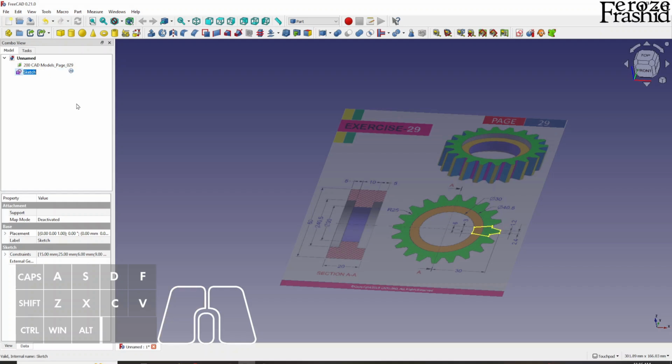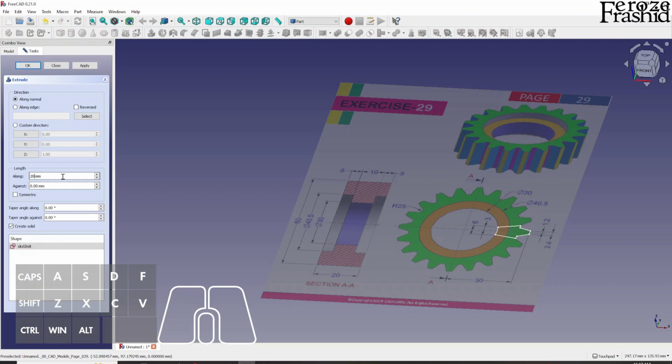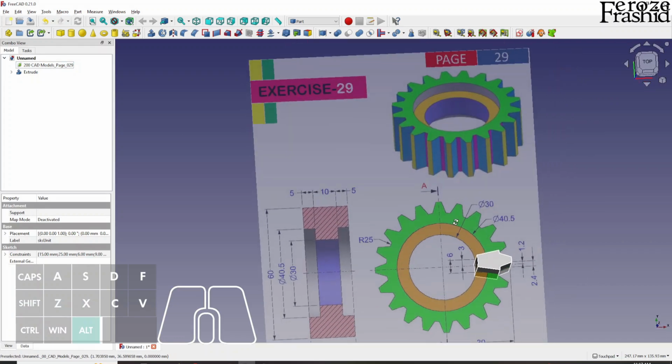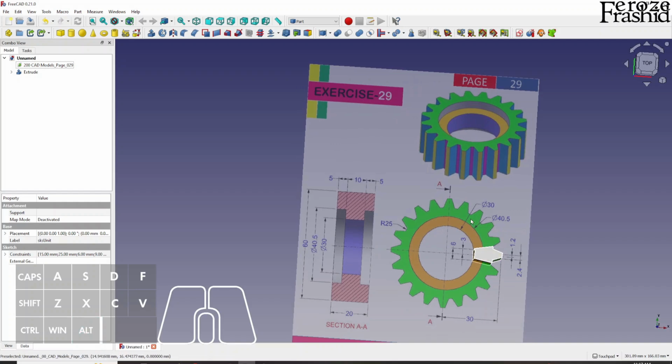So I'm going to say sketch unit. That's the one. I want to pull it up by 10, 5 and 5. So that's 20. So let's pull that up by 20. And while I'm doing that, let's make it symmetric. So that's our one tooth. We got one tooth. Now I want to repeat that however many times. So 1, 2, 3, 4, 5.